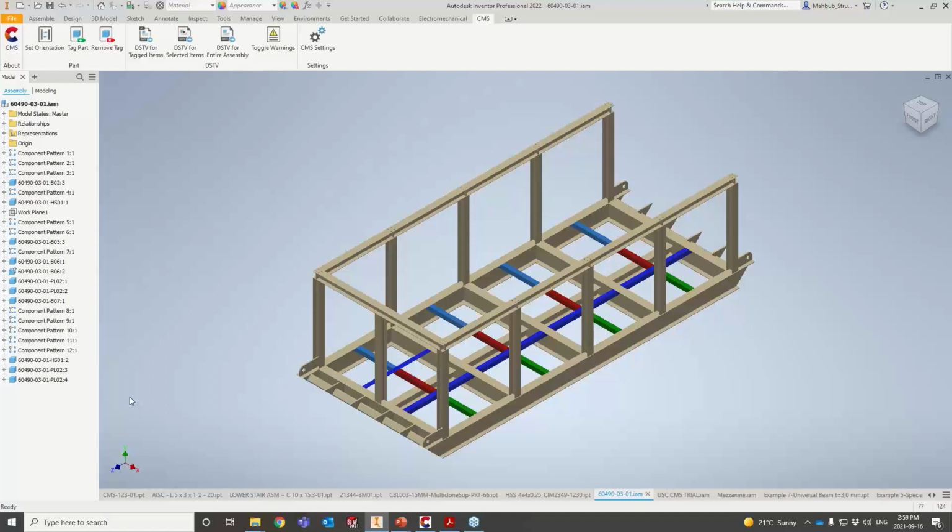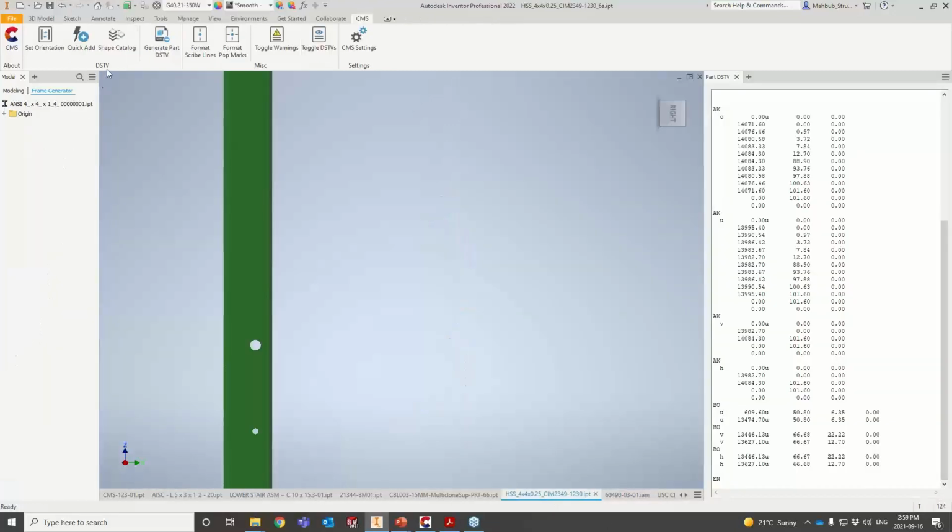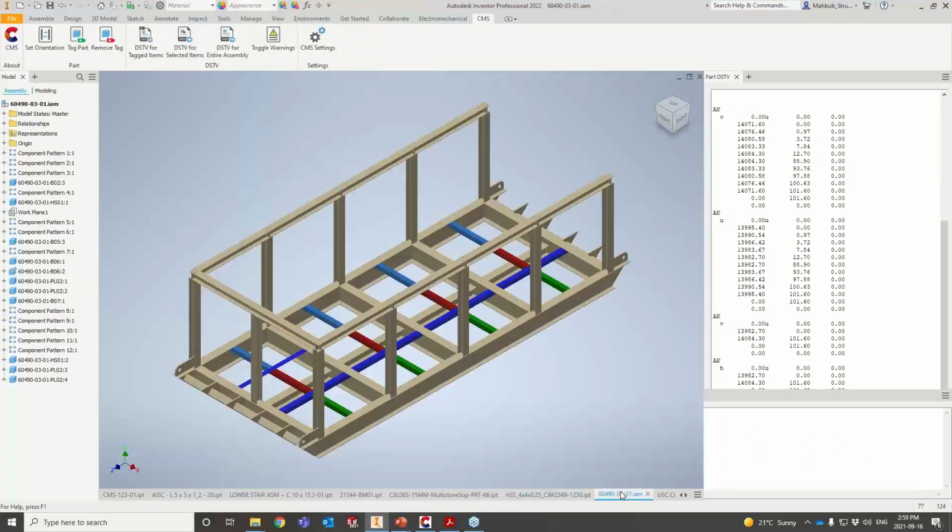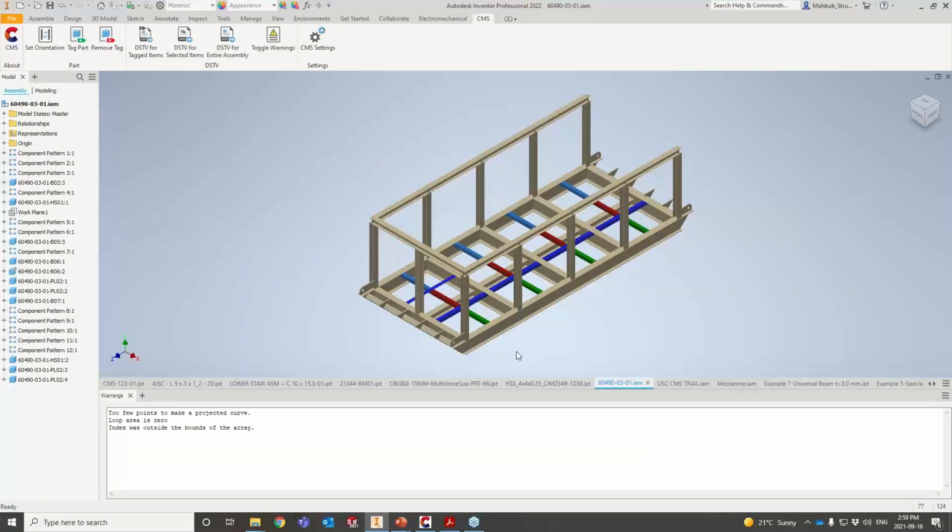What we look for is, again, that you have your shape size information on your part. If you don't have it, we will not be able to process them, because the software looks for that. Adding your shape sizes is easier on the part level, not on the assembly level. So make sure you have that information ready. As long as you have the shape size information on all of your parts, then creating an NC1 file is just one single click.